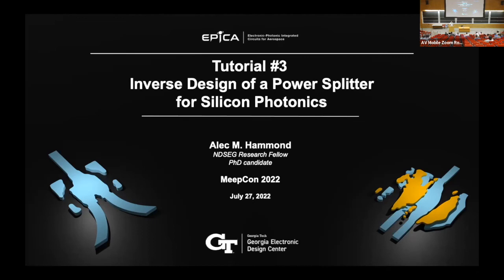Yeah, so that's kind of another hyperparameter, right? How do you choose a suitable ratio between the two? My rule of thumb is I typically just map to the actual Yee grid resolution, which is a factor of 2 larger than the normal MEEP simulation. Sometimes we like to go significantly higher resolution such that we can easily, as I said earlier, interpolate onto really fine grids that we need for our GDS layouts at the end of the day.